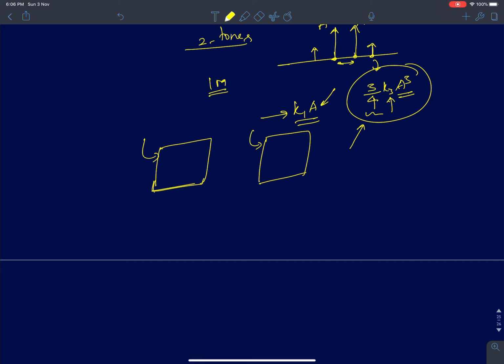As we increase the signal amplitude, the gain was reducing, and it also tells you about interference strengths from a single interferer. But when I have two interferers, the strength of the signal they give rise to is not directly related to the 1 dB compression point. So we will need some other metric, especially for narrowband systems.